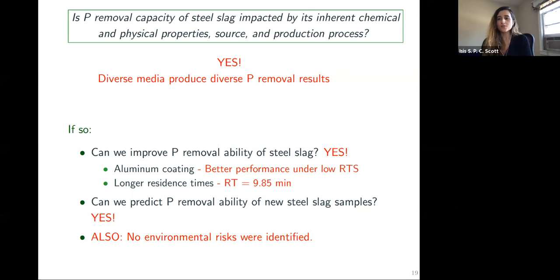The pH is not a problem, just because it is quickly equilibrated once it reaches the nearest water body. But in terms of alkalinity, we don't like to use those steel slags that have a higher buffer capacity. So we look for the ones that have intermediate buffer capacity, just to make sure that it can keep those high pHs for calcium precipitation to occur, but it won't be a problem once the water is drained out to the ditch.